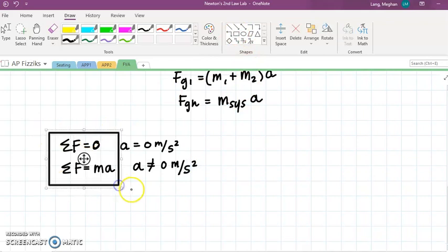So make sure when you're solving these questions, you are drawing a free body diagram. So first step, free body diagram. Second step, sum your forces. You need to be doing this for every single question, okay? And the sum of your forces is your equation.